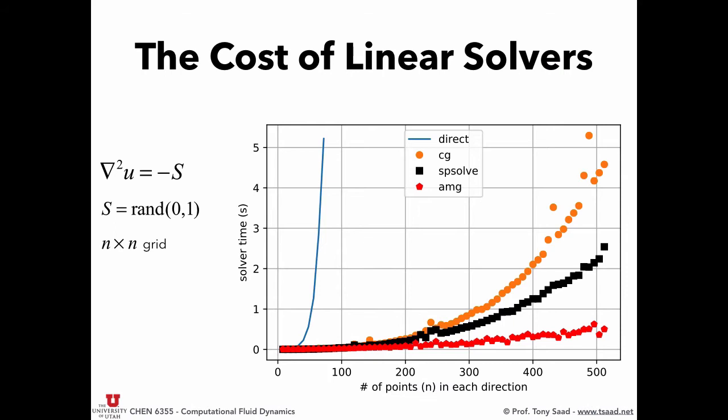So the power of using iterative solvers. Now do this over 1,000 time steps. It's going to matter. A solver that costs you half a second to solve the system of equations over 1,000 iterations versus a solver that costs you 3 seconds over here, that's going to matter. That's going to be a big difference, okay? And it's a big deal. Picking a good iterative solver is a big deal, okay?